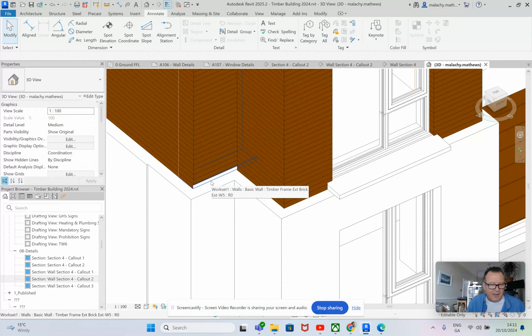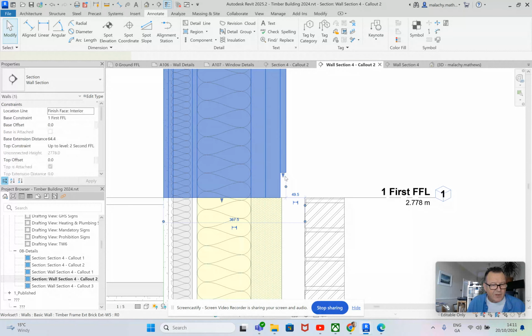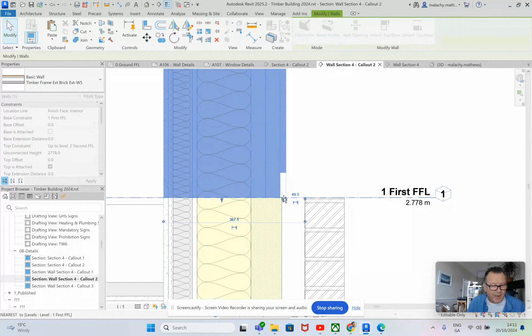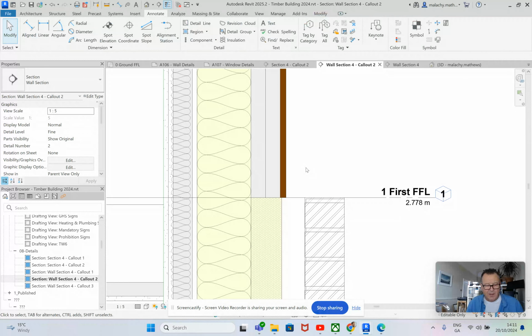If I was going to model that drip tray, I'd probably do it as a wall sweep, something like that. Now I know you've done a bit of work with Tom on that, so that might be the handiest thing to do, is to create that wall sweep and put it around there, and then you can lift the external piece up. All right, now let's get back to where we were. So that's one option, but by doing that it does affect the model.